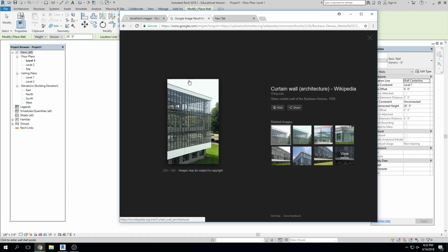The way that a curtain wall works, and I'm just going to make a weird little connection here, is that you have a system that can be hung off of the structure in some way or another, right? Something like that maybe. So you have these structural plates, and the curtain wall is somehow connected to the structure of the building, and it's hung off the structure. So it is self-supporting, but it's not like storefront where it's in a structural opening, it's hanging off the structure.